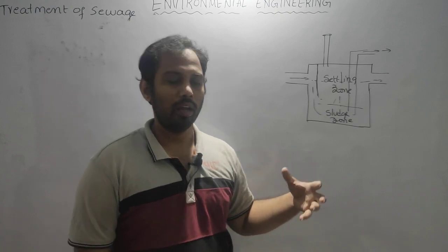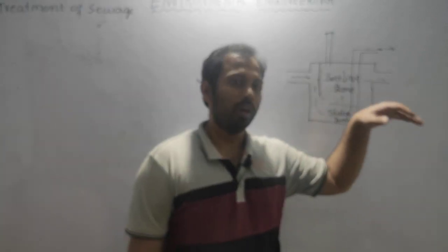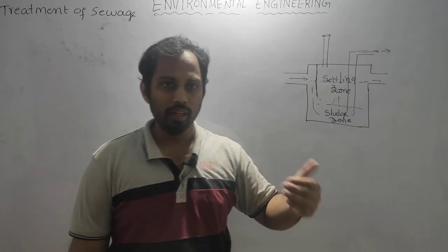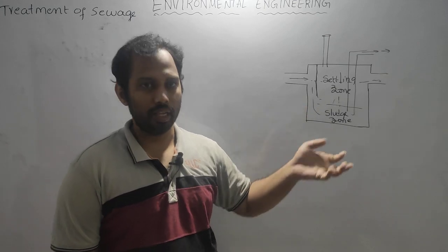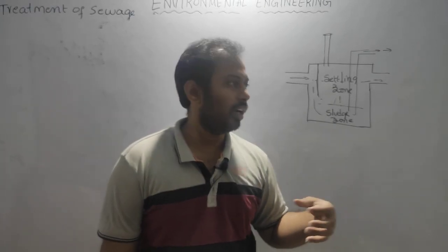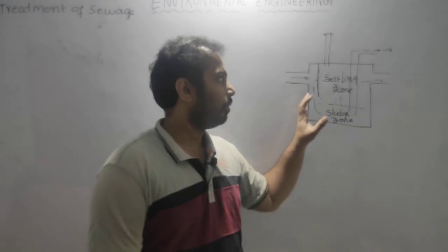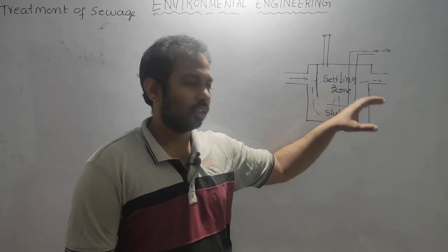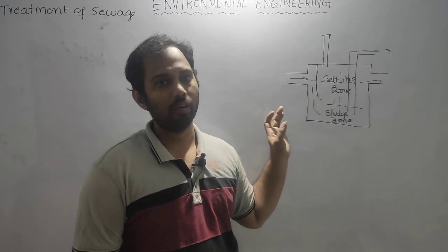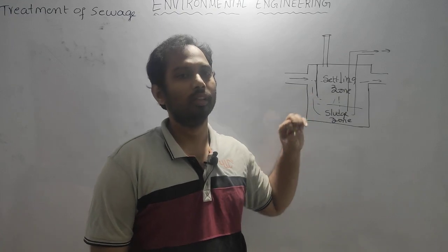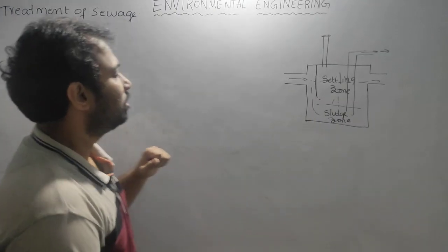So those kinds of mechanisms, the effluent will not go directly into the drains; it will be land irrigated using soak pits and dispersion trenches. So likewise we work. That is the complete process flow, the complete process of the septic tank.